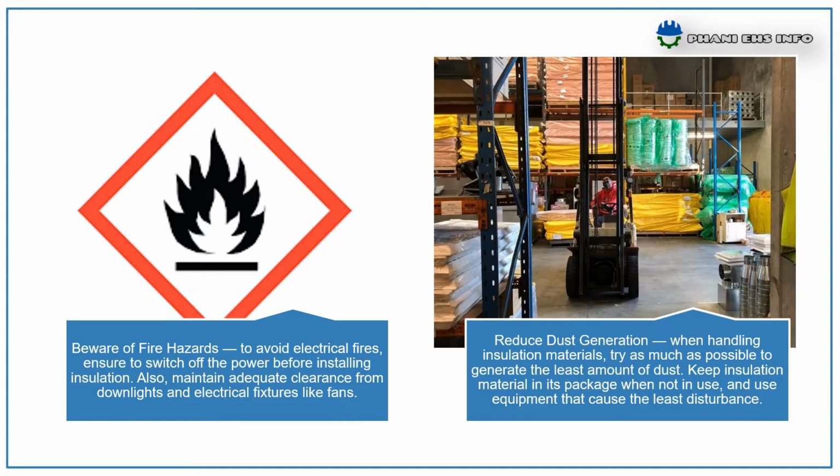And last one, reduce dust generation. When handling insulation materials, try as much as possible to generate the least amount of dust. Keep materials in its package when not in use and use equipment that cause least disturbance. These are the safety tips at insulation works.